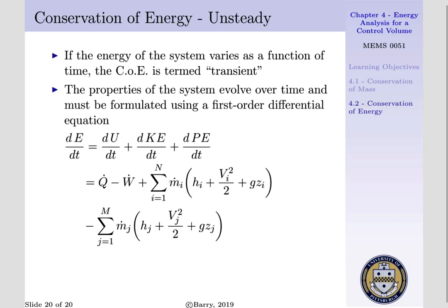That means the time rate of change of our total internal energy plus the time rate of change of our kinetic energy plus the time rate of change of our potential energy may be non-zero values. Oftentimes, we are not interested in the time rate of change of our kinetic or potential energies, for we assume these to be negligible, and rather we're focusing on the time rate of change of our total internal energy. And this would be equal to the right-hand side of our conservation of energy equation, as we are familiar with.